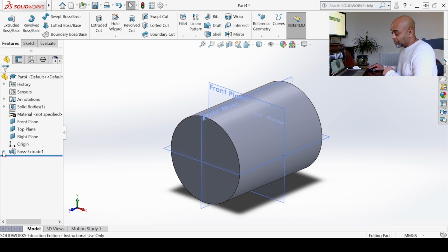We have the layer system here. If I were to open that chevron there, that is regarded as one step. That bundle right there has made that cylinder. If I wanted to make another cylinder, I'd probably have to draw another sketch and maybe extrude that out, and that will be bundled in quite nicely like that.